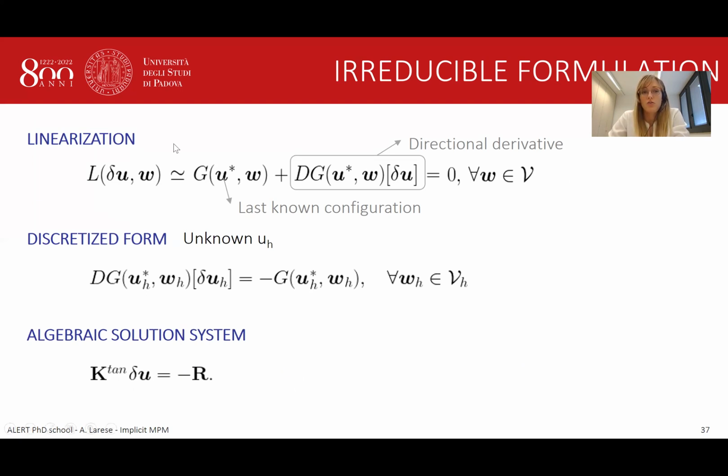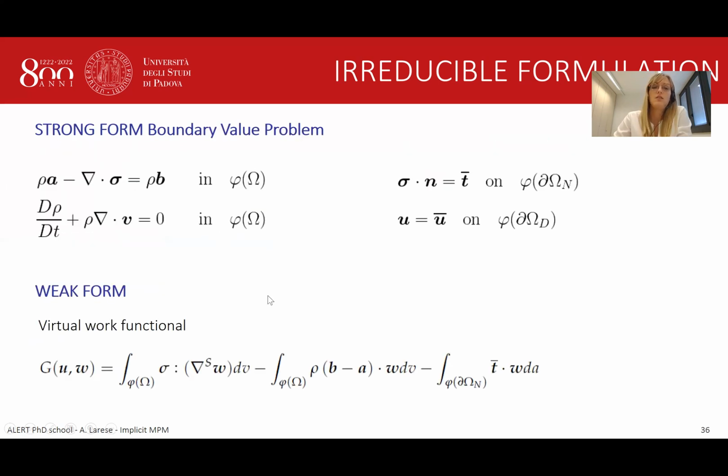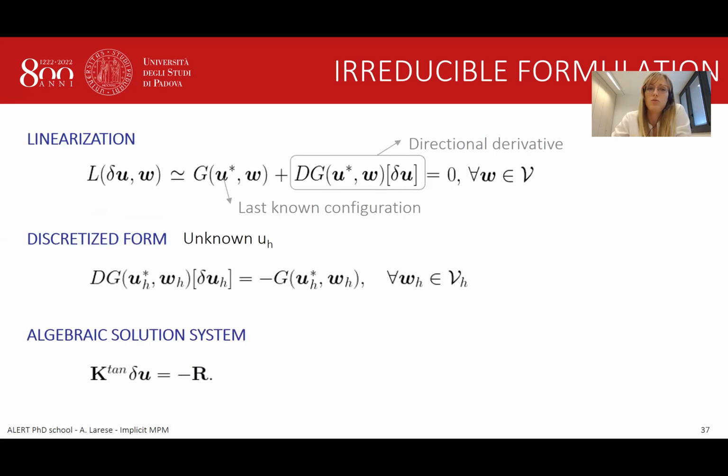It's not sufficient to reach the weak Galerkin form of the problem, since this is still a continuous form and still a nonlinear form. As I said before, we are unfortunately dealing with very complex problems which are highly nonlinear. So what we need to do is to linearize this problem, and this is classically done using Newton-Raphson procedures or similar approaches.